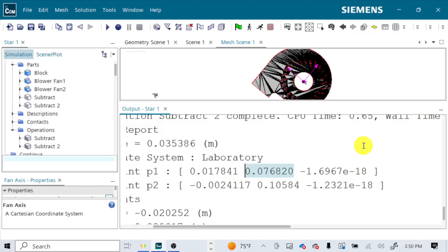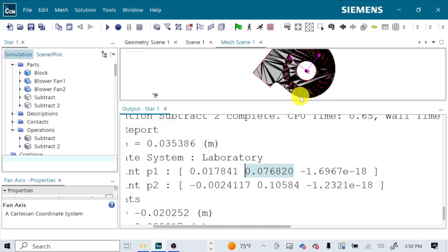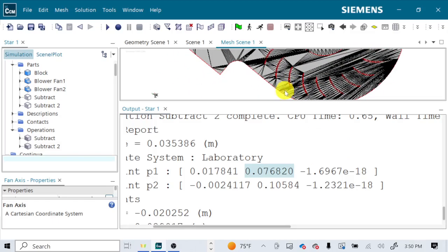We want to go just past them. We want to go a little bit below the minimum, a little bit above the maximum. Now, how much depends, in part, on how close anything is to the blades. Some blades get extremely close to the walls around them. You might need to get really, really close to the tip of the blades if you have something that is stationary right next to them. But we don't have anything stationary that's right next to them. We can afford to go a little ways away. So let's try and go 5 millimeters out in both directions.